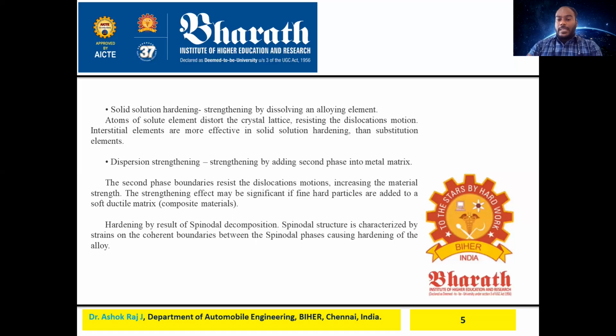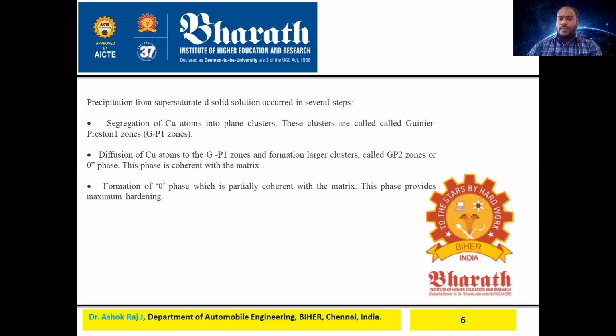And hardening results from spinodal decomposition. The spinodal structure is characterized by the strain on the coherent boundary between the spinodal phases, which causes hardening of the alloy. If you harden the alloy, as I already told you, you can increase the tensile strength and fatigue properties. And precipitation from the supersaturated solution occurs in several types.